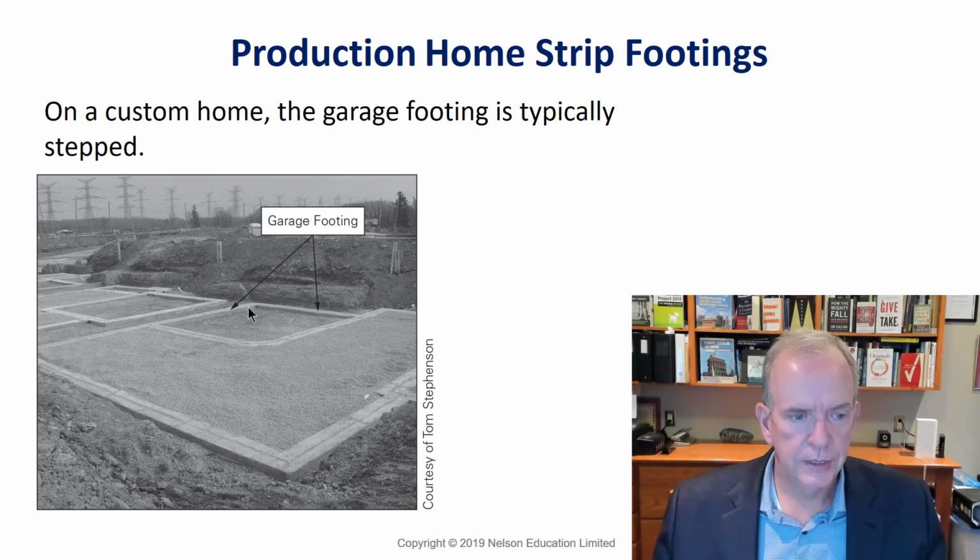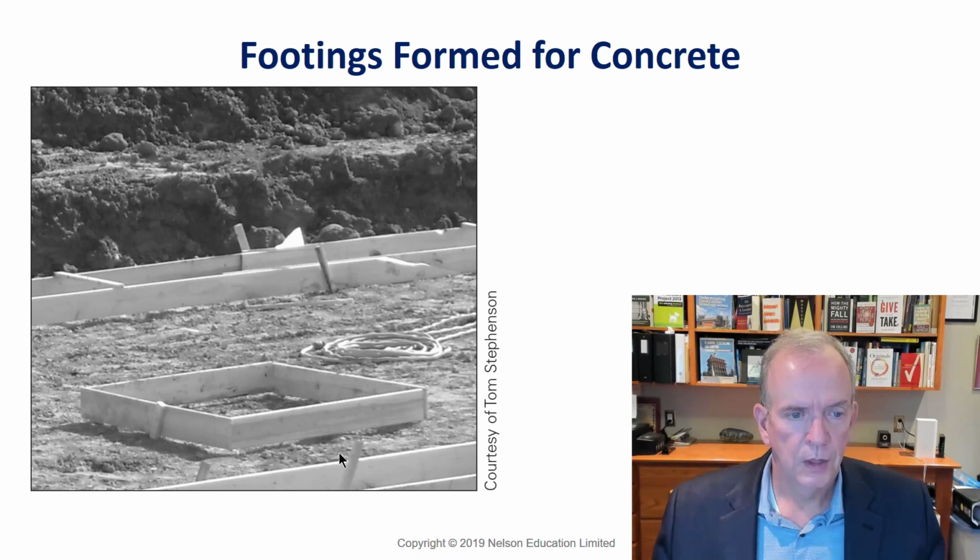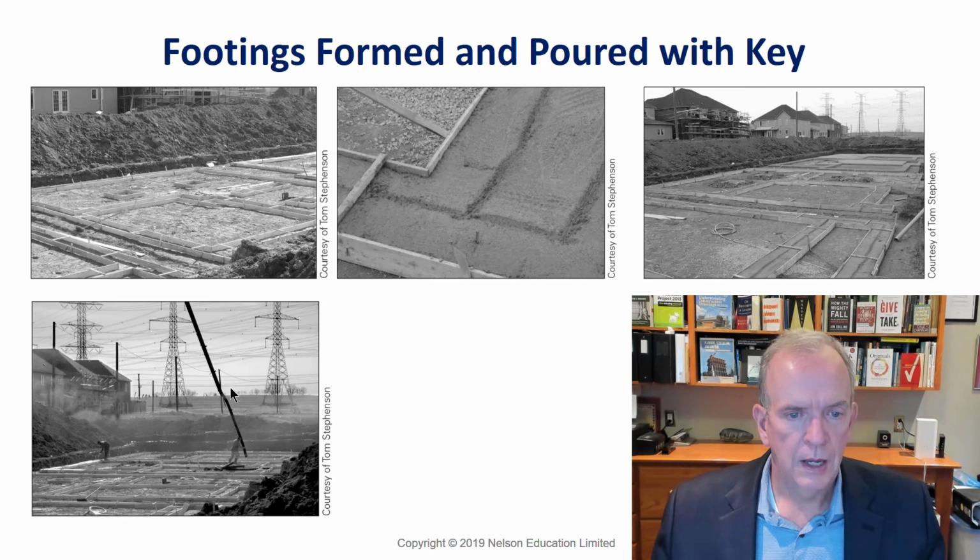In residential, they sometimes do a lot of shortcuts, most of the time, any that I've ever seen. Somebody runs around either with a piece of wood or the edge of a shovel and just kind of puts a groove into it. Truth is, once you put the concrete slab on the inside and the earth on the outside, it's not going to move anywhere. So the footings are formed, they're pegged, they're formed so that they can be poured. There's that groove that I was mentioning about, the keying.